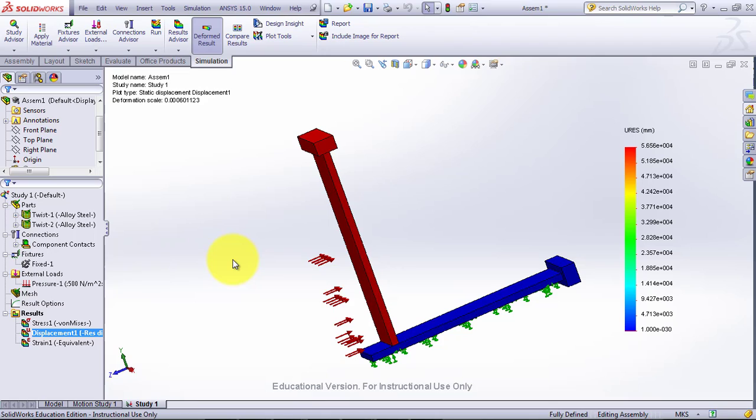Using those techniques, the soft springs and the draft mesh, are two key things. Unless you're confident it's going to work the first time with the setup you have, I would even run that the first time just to make sure everything looks good. But it's probably good just to run with your basic conditions and a good mesh, and if it does fail, come back, use the soft springs and the draft mesh so things can fail quickly and you can get some information about what's going on. Hopefully things are just flying away, and you need to lock them in a little bit more with the fixtures.